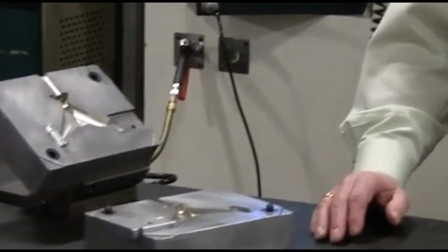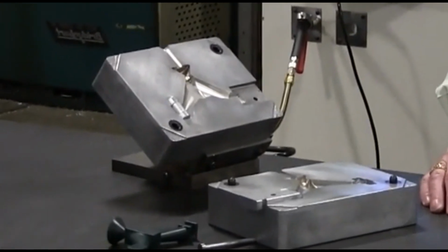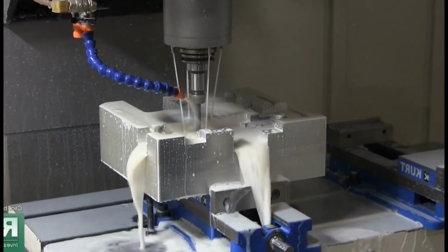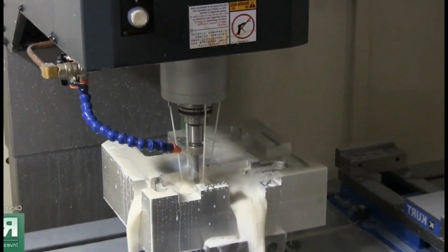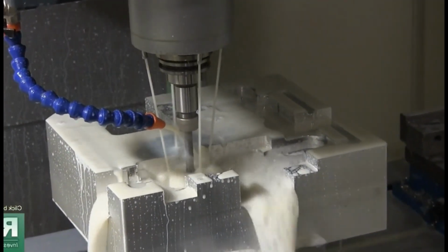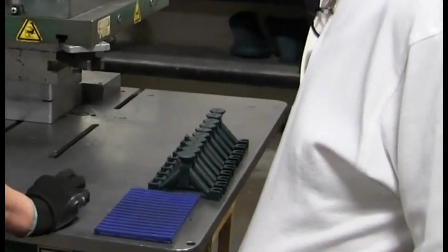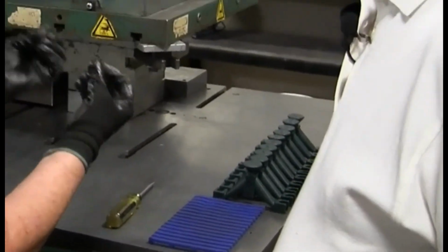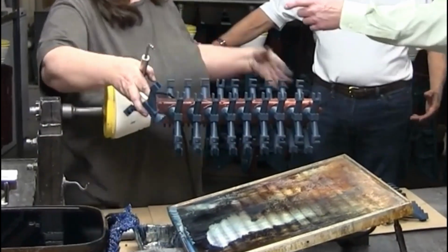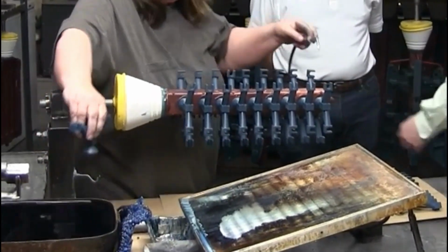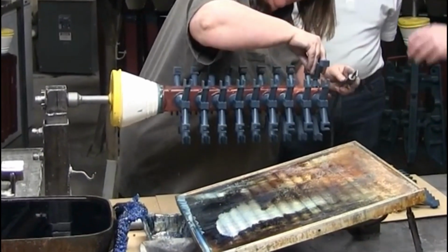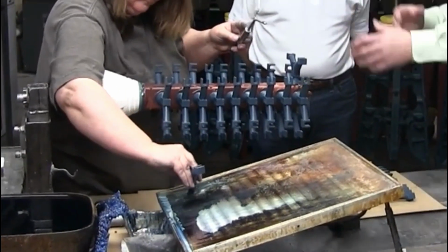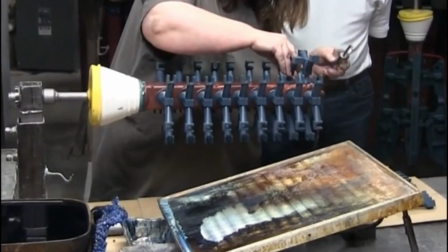The mold used for the wax pattern production is made of metal, with the cavity inside created using a CNC machining center to ensure accurate shape and dimensions along with a good surface finish. These wax patterns are often made in large quantities if the same part is needed for mass production. To increase productivity, multiple wax patterns are attached to a central wax sprue, forming what's called a wax tree. This allows several parts to be cast at once, speeding up the production process.